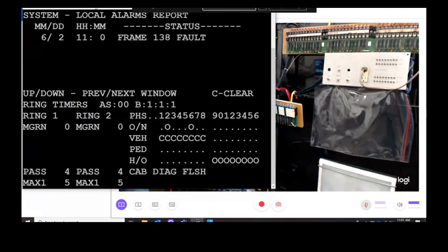I can send you to the back of the Siemens controller manual where it says commands and responses. It lists all the frame numbers and the faults and what they go to. So frame 138 would say TF, Terminal Facilities 1, which is our back panel, and then BIU number 1.